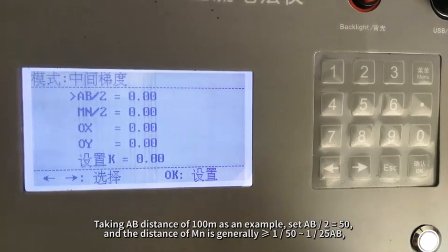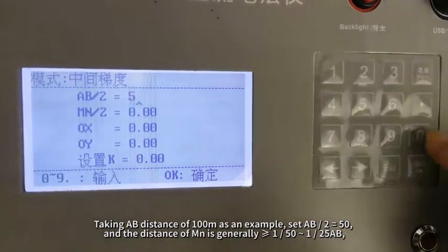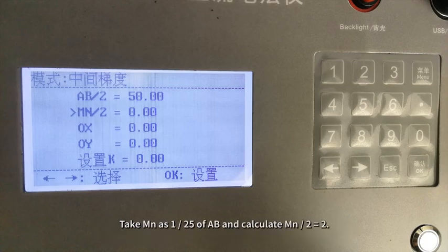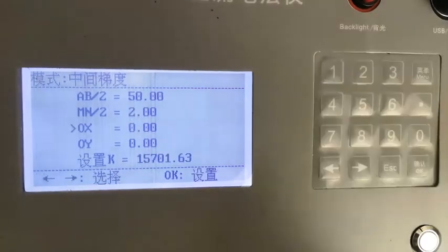Taking an AB distance of 100 m as an example, set AB/2 equals 50. The distance of MN is generally 1/50 to 1/25 of AB. Take MN as 1/25 of AB and calculate MN/2 equals 2.